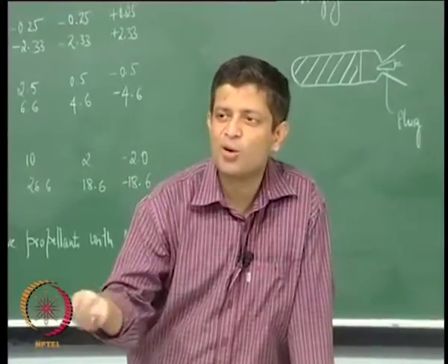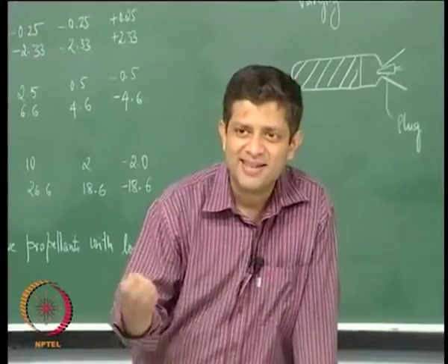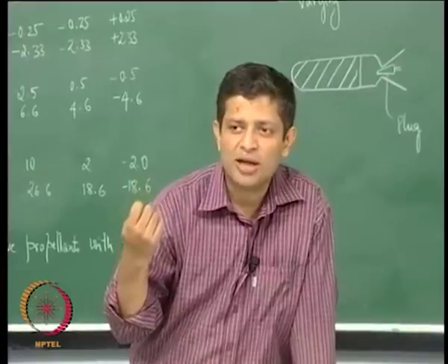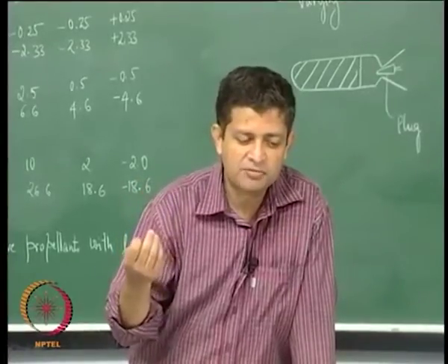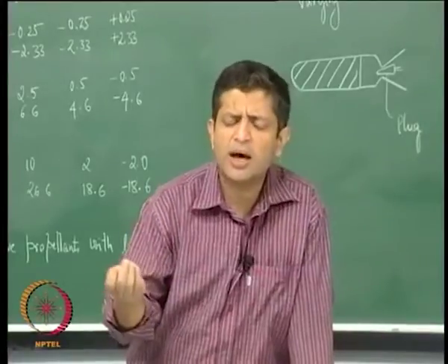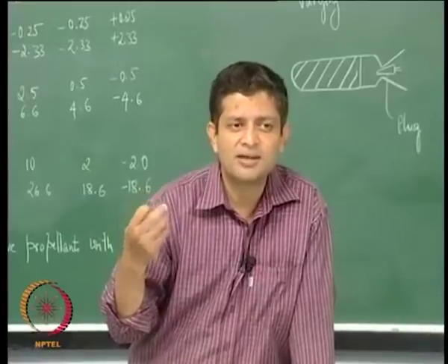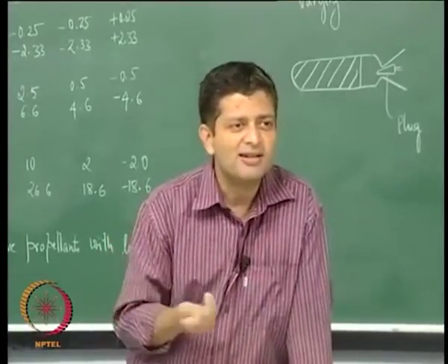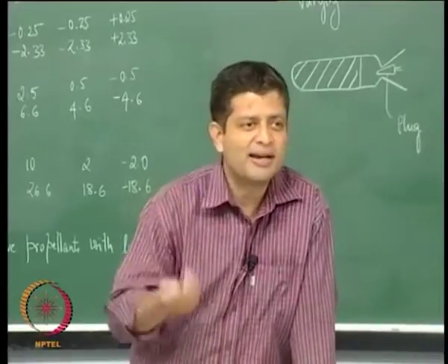So, one way is to have a, best is to have a low n and low sigma p. If that is not possible, then have something wherein the throat area is changing. This cannot be a solution for a large missile application, primarily because this plug is exposed to high temperature gases, and if the burn time is very large, it will tend to burn itself out, which again will dramatically change things.